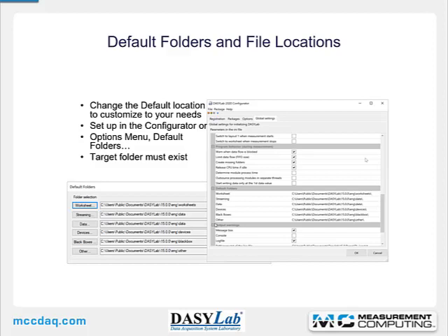Where are my files? DASYLab defaults folder locations to the public user folder on your computer. If you want to change the default location of where those folders are on your computer, once you've installed DASYLab, in the DASYLab configurator, which is part of installation initially, you can change the location of the default folders to any other folder on the computer.